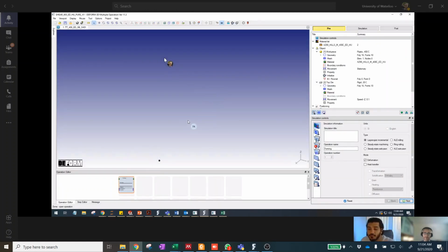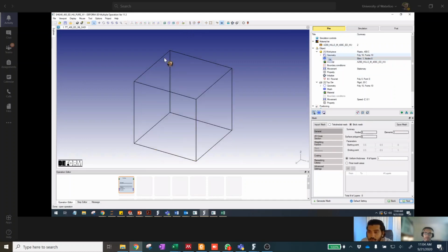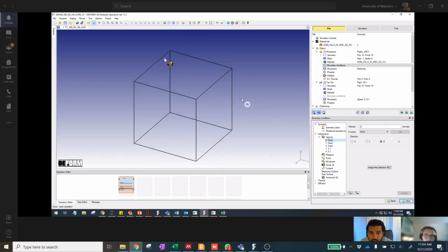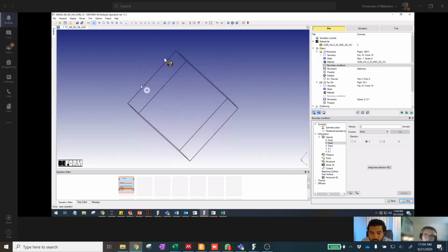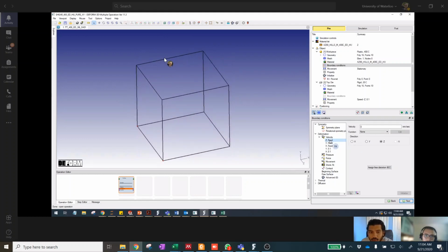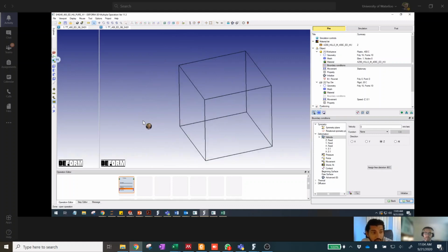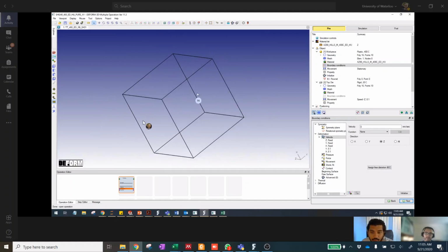One thing that I did notice was when I constrained both faces, the simulation doesn't run. Let's get into the orientation. I'm going to fix this node in the Z direction. Realistically, you could try fixing nodes 1, 2, 3, and 4. I'm going to fix this entire face in Z and leave this face untouched, because when I do that, it crashes. Exactly, if there's no, okay, agreed.